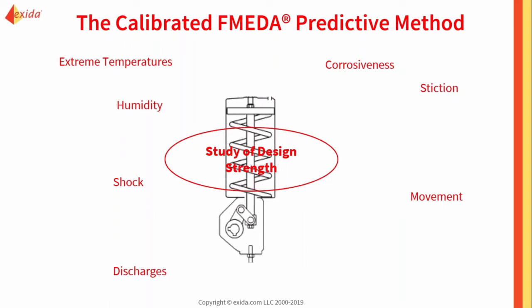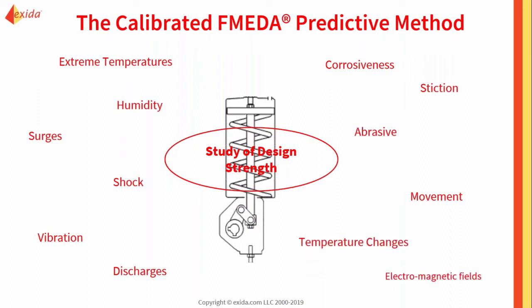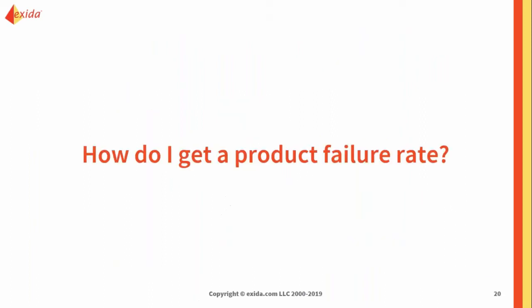And these failure rates, the failure modes, the diagnostic coverage, useful life, even proof test coverage can be predicted by the FMEDA study of the design. And depending on your environment, depending on your application, low demand or high demand mode, you will have different stresses and strengths coming into your analysis.